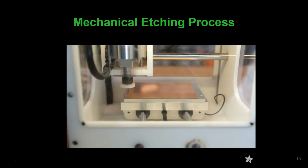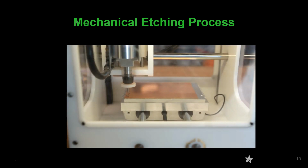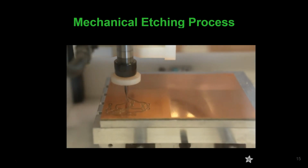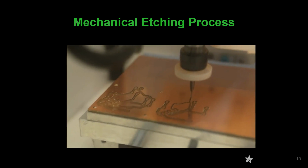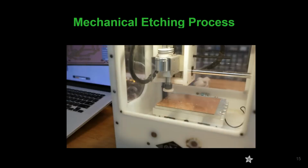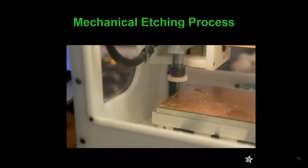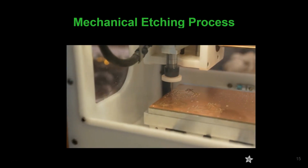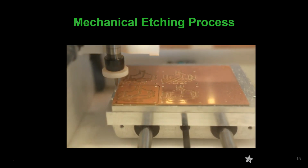There's a number of chemicals you can use for etching, but the most popular is probably ferric chloride. I'm using a mixture of 1 part concentrated ferric chloride to 1 part water. Now be careful, as this stuff will stain almost anything and easily mess up any metal surface. You'll definitely want to avoid skin contact and keep a well-ventilated work area.